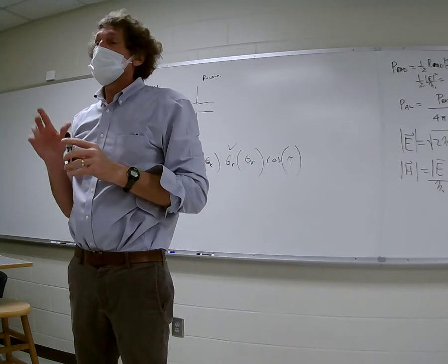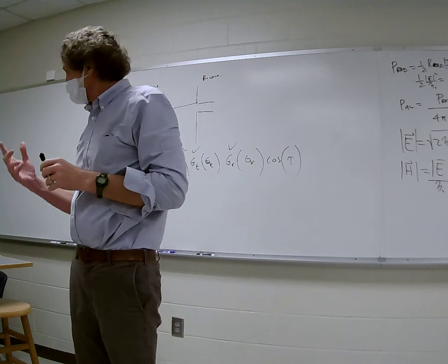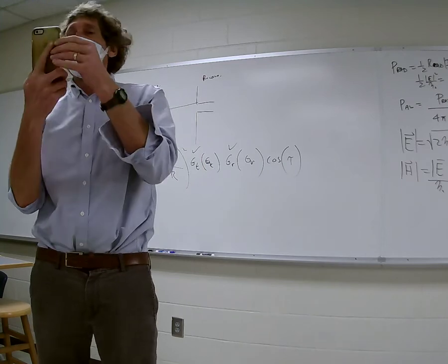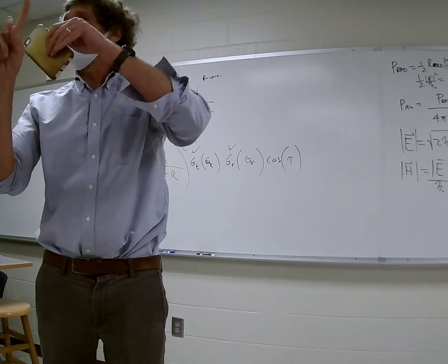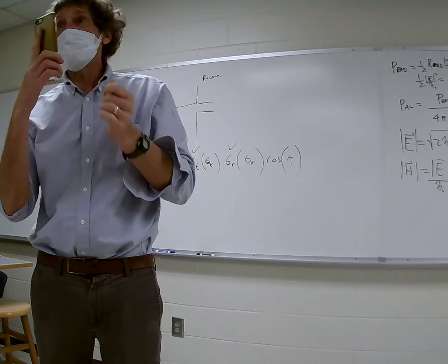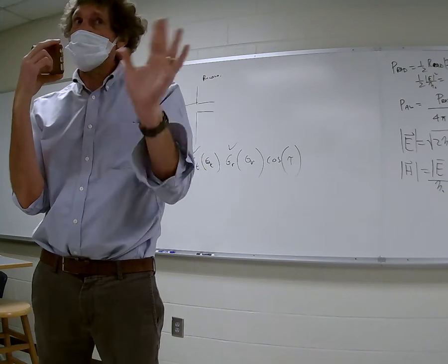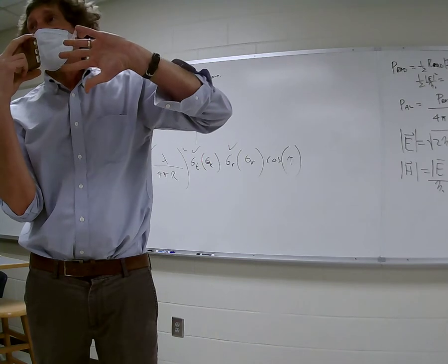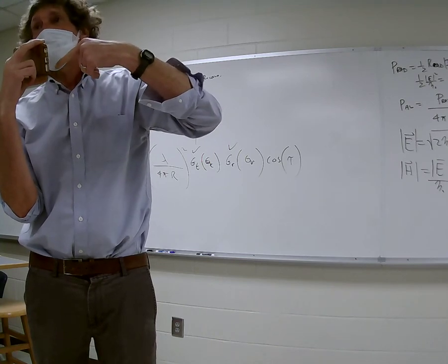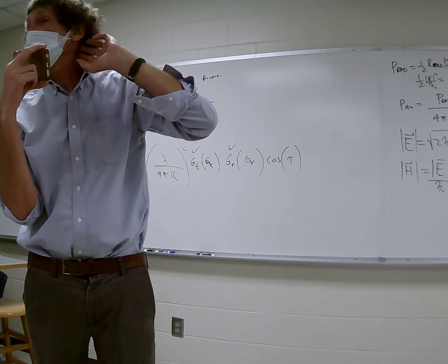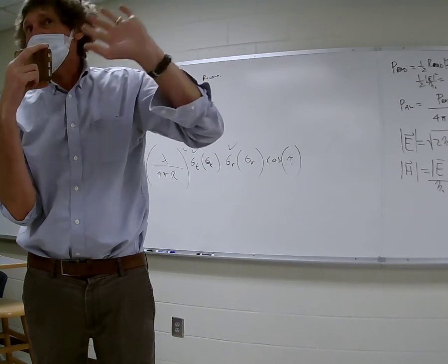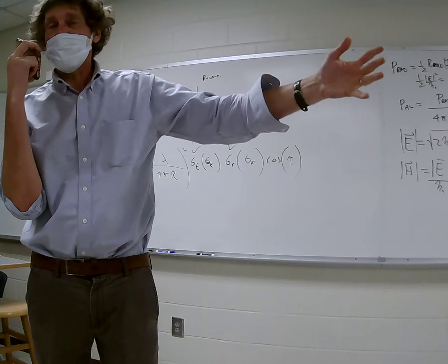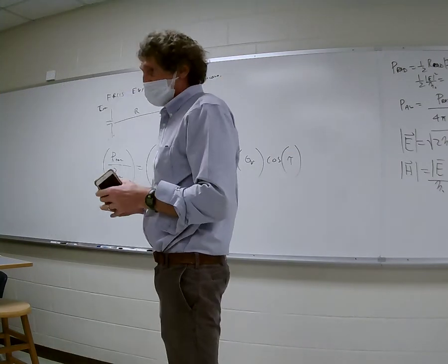Follow me? In general, what they do is if you hold the cell phone up like this, anything polarized in the vertical direction you'll catch like this. But if you take this and do this, now if you're close to the ground, there's a lot of reflections. You're going to find the signal strength's going to fall off. Because they have automatic gain in these phones and everything like this, you might not detect it with the voice, but all of a sudden packets will start dropping. Have you ever had packets drop where you're talking, there's like nothing, talking nothing? That's what's happening there, probably.